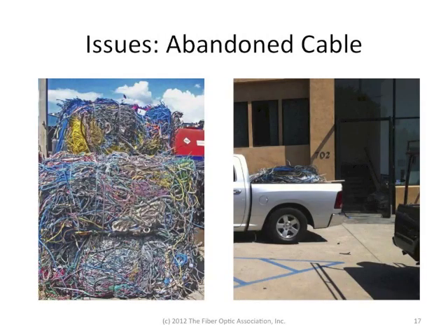One of the issues we have to deal with in premises applications is abandoned cable, especially during network upgrades. Many buildings have tons, literally tons, of abandoned cable that needs to be removed in order to meet the requirements of the National Electric Code. Your contractor needs to understand where those cables are and how to remove them without damaging other cables in the building. The good news, however, is copper is expensive and all this cable can be recycled for a pretty good amount of money.